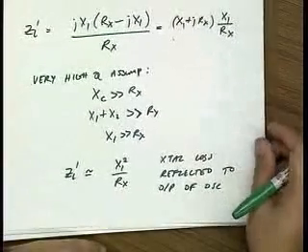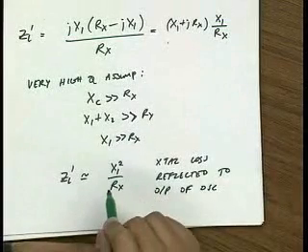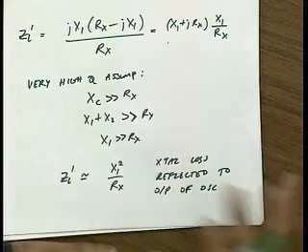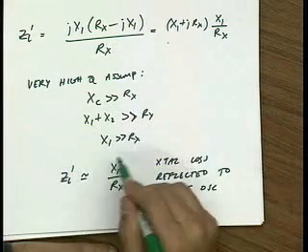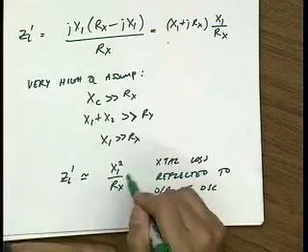So if I compare the loop gain at an overtone frequency, because this term is smaller, in fact, I should correct myself, I get more loading at the overtones because this is a lower impedance, because it's in shunt. So let me write that down.